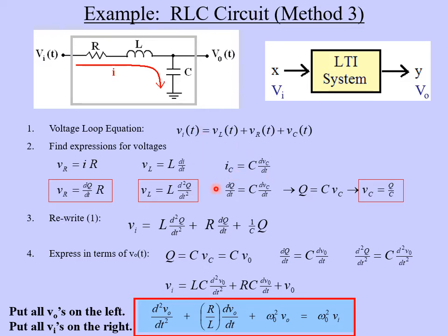All right, and then in this equation here, on the left we have I, which is dq dt, and over here we have the dv dt, which stays the same. And by the way, this can be solved. What you can do here is integrate both sides of this equation, and you come up with an equation you might remember from physics or electrostatics. The charge on a capacitor is equal to C times V, the capacitance times the voltage across the capacitor. So Q equals CV comes from this; it can actually be derived from this current formula up here. So the voltage on the capacitor is Q over C.